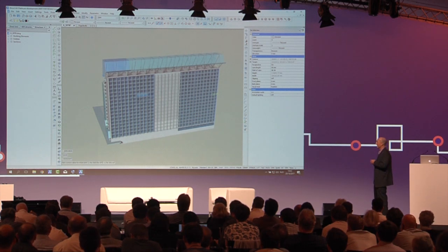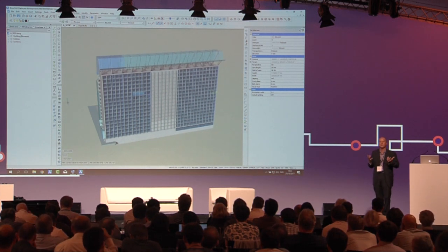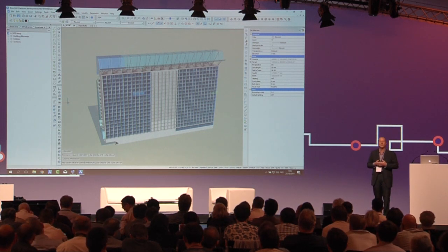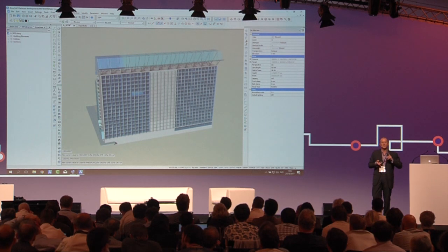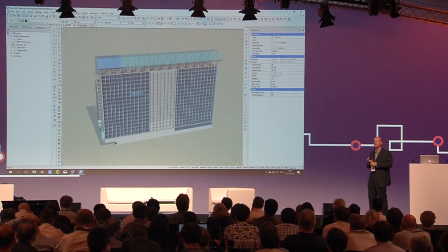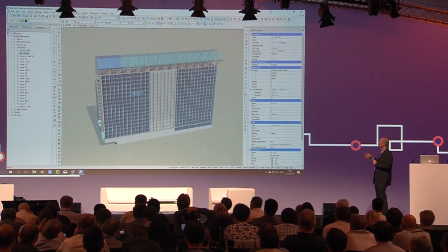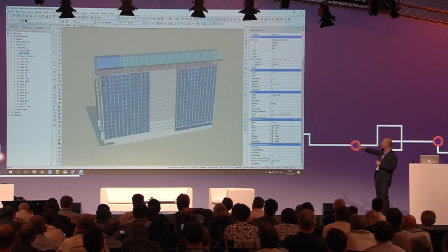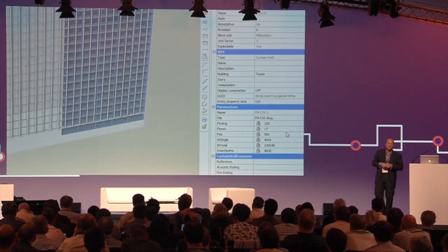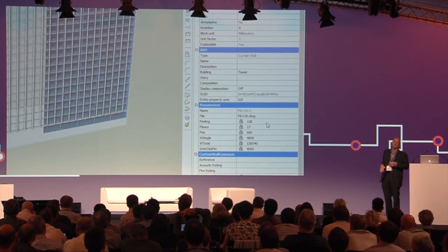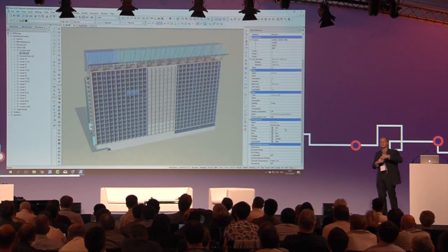And in this case, we've set up this whole rear facade as an array. This parametric component has glazing components, it has a catwalk, it has vertical shading fins. And if we highlight the whole array, then we have parameters that we can adjust for that overall array. So let's say we didn't want the same uniformity across the whole vertical steps of the facade.